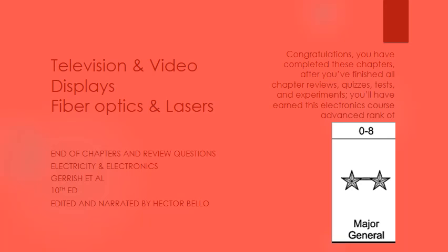All night vision devices use tube technology to pick up the image and display it, but they vary in how they amplify the electrons. In original models, the light was converted to electrons, and then the optic system focused the electrons through an anode and accelerated them so they could hit a phosphor screen, creating a visible image.